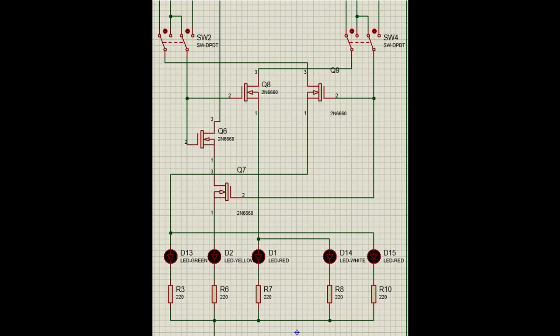When the push buttons aren't pushed in, that is in their normal state, they are connected straight to the power supply MOSFETs. But when the red LED's push button is pressed in and latched, it turns off both yellow and green at the signal and supplies straight 5 volt to that LED from the power rail, thus making sure only red can stay on. The same was done for the green LED's push button too. Each signal needs a 4 P channel IRF9530N MOSFET assembly to control the switching.